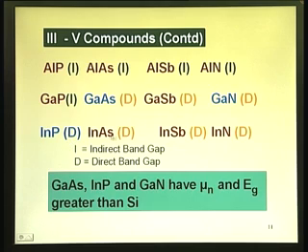Indium phosphide, you can see whole lot of them. The indium atomic number is 49, big atom. In fact, its tetrahedral radius is 1.44 angstroms compared to 1.18 angstroms of silicon, huge. Okay, you can say 1 angstrom, 1.44 angstroms, but look into the atomic scale, you go down, stand with the atom, 1.11 or 1.18 for silicon, 1.44 for indium, it is huge difference. So, they form the direct band gap semiconductors.